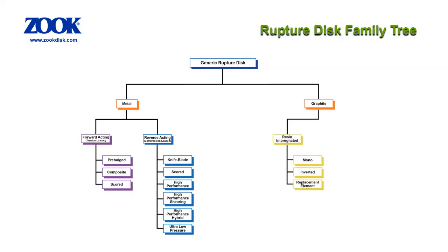Resin impregnation is the first and most common process used. Various resins have been used over the years, but typically they are phenolic based. Through a process that includes pressure, vacuum, and temperature curing cycles, the graphite pores are filled with cured resin that renders the graphite material impervious and suitable to be used as a graphite rupture disc. Resin-impregnated graphite provides good corrosion resistance, inert material with non-ion contamination, temperature stability, and predictable results.